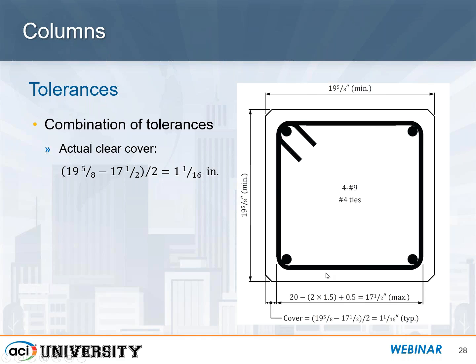This distance then can go down to a maximum of 17.5 inches. And as I had mentioned during our first session, this is the perfect storm of tolerances all happening at the same time. Can it happen? Sure. Does it happen all the time? No, but it's good to be prepared, and try to avert these types of problems before you get the phone call from the construction site.